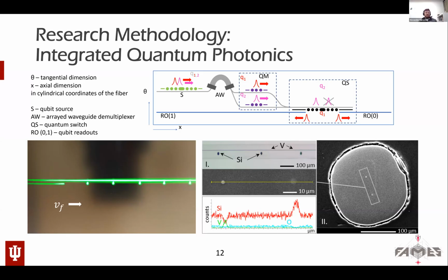And then first attempts in creating integrated circuits, so you need to draw multiple materials inside one fiber. So this is an example of drawing semiconductor and metal in one single fiber, and then breaking the semiconductors selectively. And that results, here is a core of vanadium, here is a core of silicon, that results in spherical spheres of silicon, which is a material that is transparent to 1550 standard telecom wavelengths, with a flanking vanadium electrode.